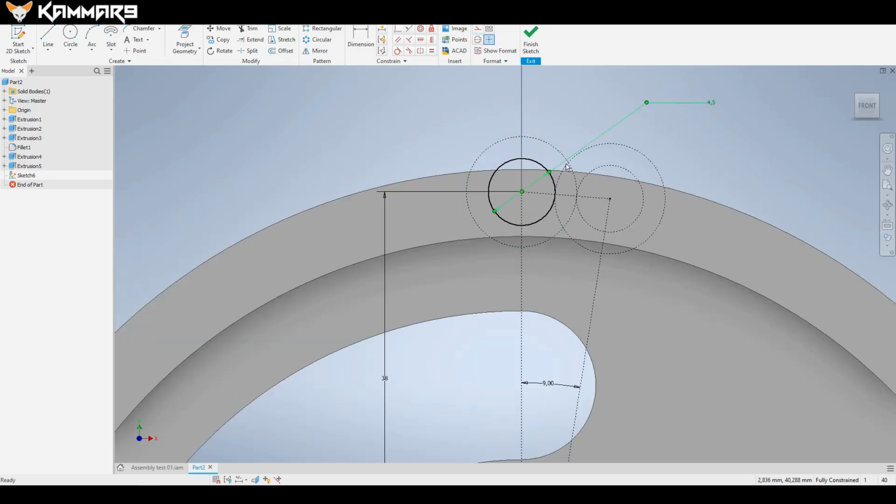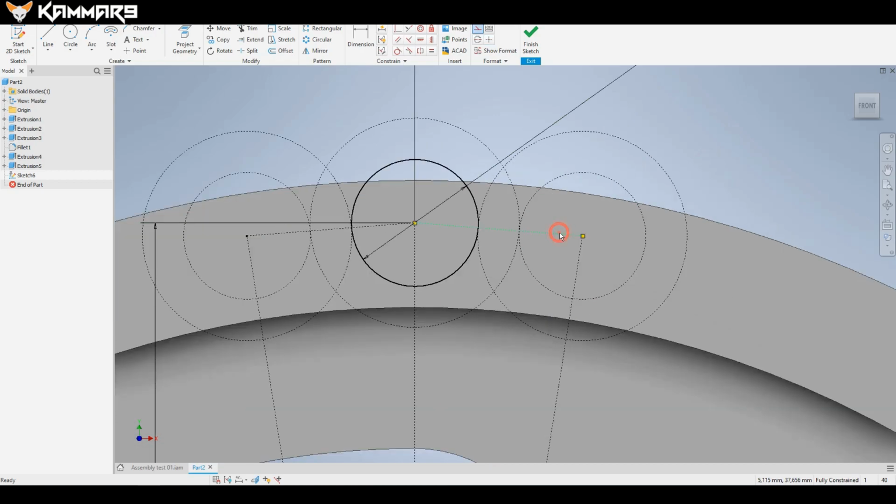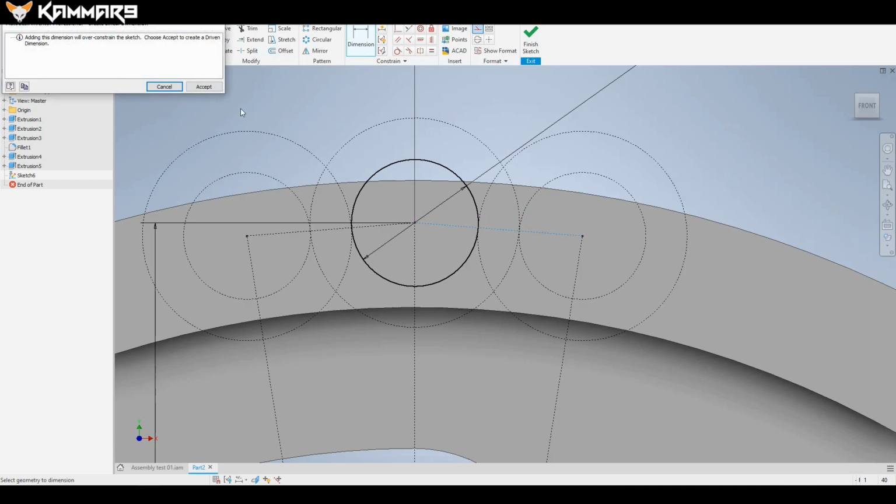Okay, and I will create another here using a mirror. I will select all of these, and you will find here mirror, use here mirror line, apply, and as you can see you have the same thing in the other direction. Make sure that you have here the distance. As you can see, you can add distance here to verify. We have 5.96, you can add it.